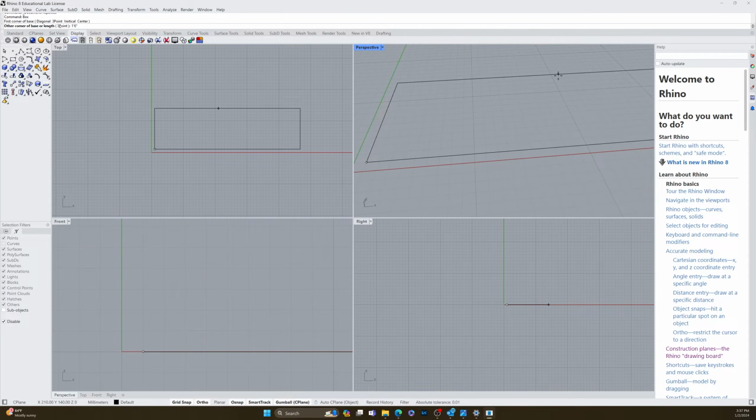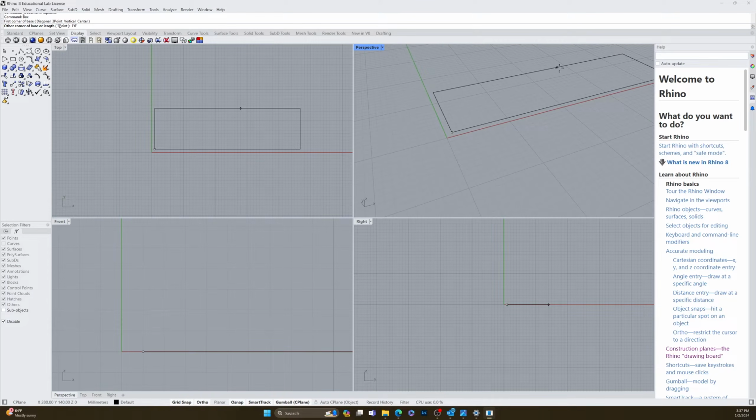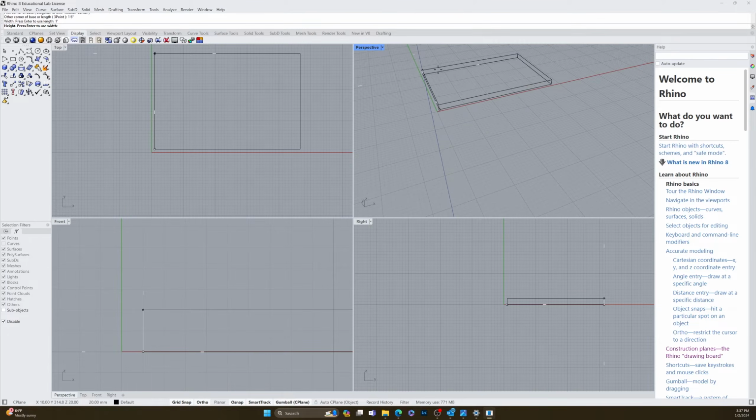And that's the nomenclature in architectural imperial units. 1'6" is 1'6". Okay. So then I hit enter, and then if it asks me the width, I can do 1', enter, and then it asks me the height. I can do 6 for 6 inches. I have to put a quote, otherwise it'll do 6 millimeters.